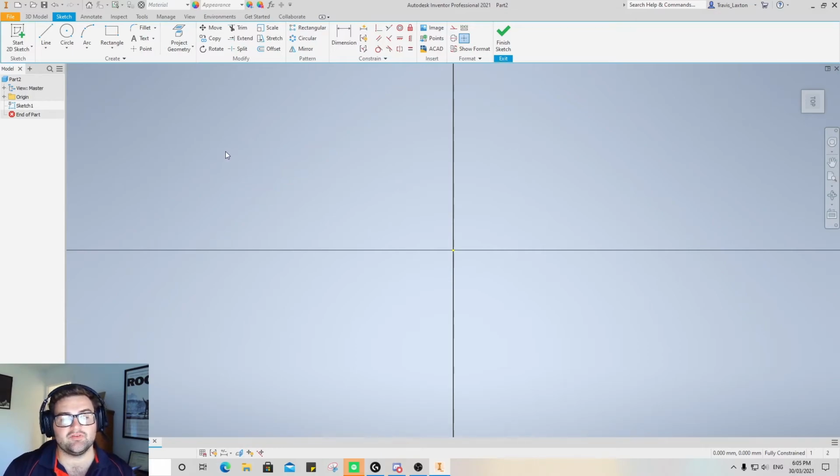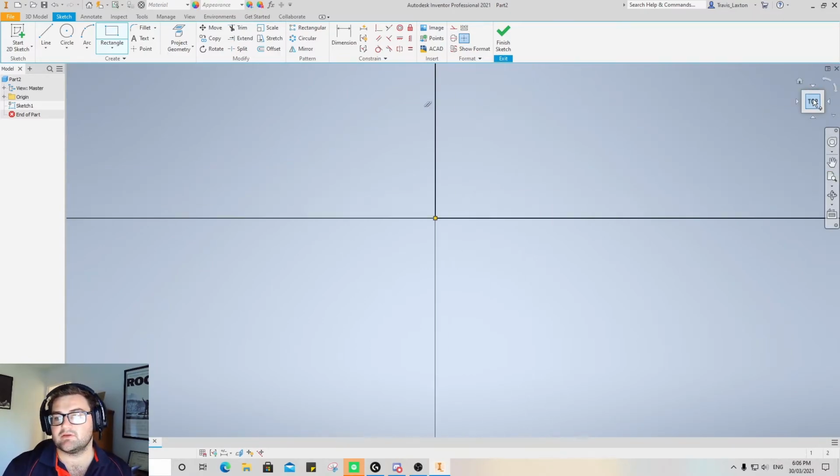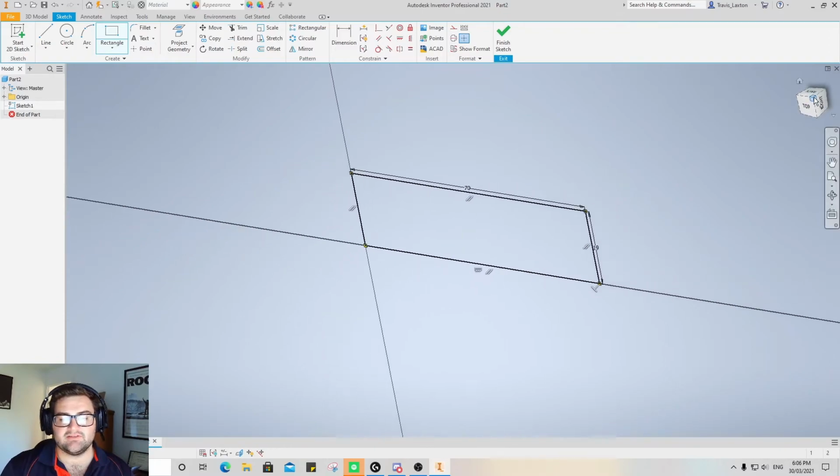Now, so if this is 450 across, we're actually going to make this the standard size of 70 by 19 pine planks that are going across it. So if I go rectangle and start here, and so I need this to be 70, tab, 19, enter. And we've got our 70 by 19 little plank end there.